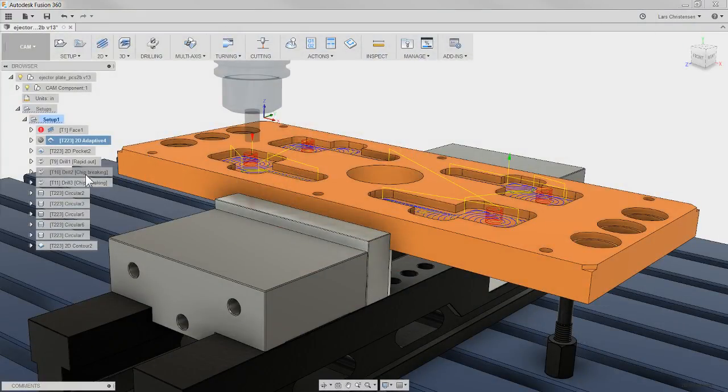This could be useful if, for example, you have two machines and one of them has a tool probe on it and the other one doesn't. Maybe you don't know which machine they're going to run the program on, so you could do an optional for the tool probing and post it out. Then the operator, if he's deciding to run the program on the machine without a tool probe, could just turn the optional stop on in the machine, and it will pass all that code. And of course, if he's machining on the one with the probe, he doesn't turn it on, and it will run. So that's what that is.